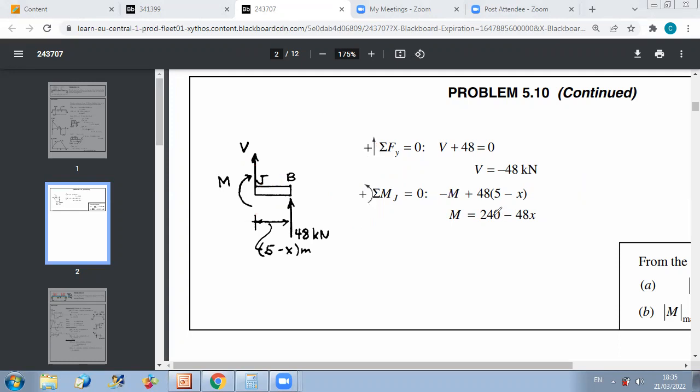So now we can also verify again that if I derive the expression of bending moment, I will get B. Okay, and since V is constant, M is linear, and since V is negative, M will be decreasing. And you can verify this again from your graph.